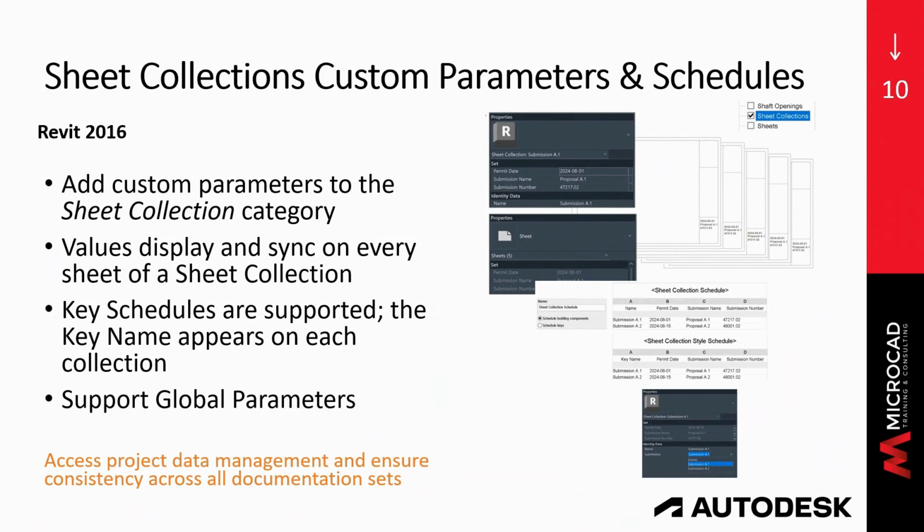So that is a perfect use for sheet collections. And now there's a couple of things that you can do. First, you can add custom parameters to the sheet collection category through the project parameters. Key schedules are now supported for sheet collections, and it is supporting global parameters, all things that I think are incredibly valuable.